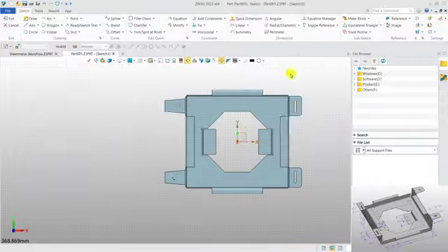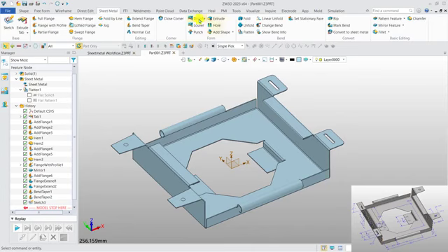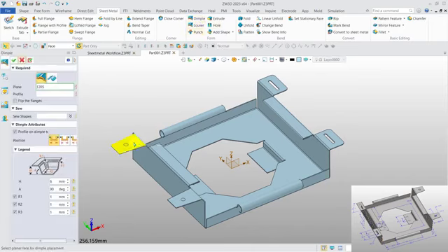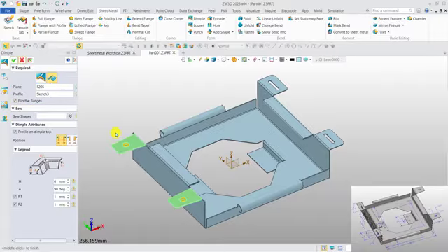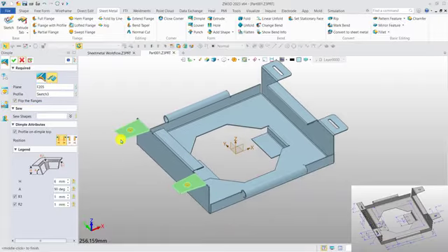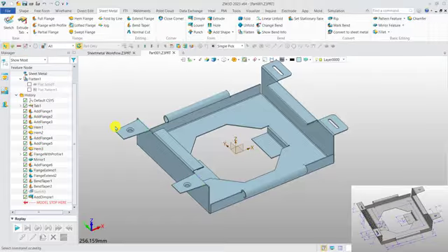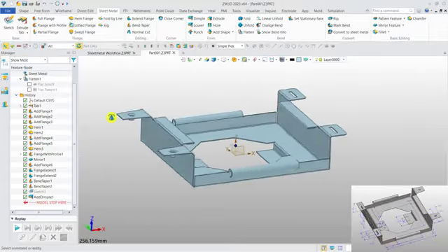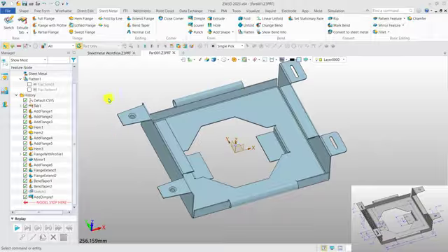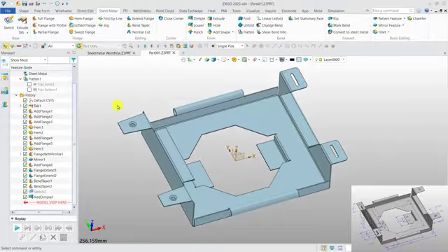Okay, now we exit and create dimple, select the plane and the profile. And here we use the other side. We flip it, and we need to flare the hole. Now we get a result. Now we can check it if the result is what we want.